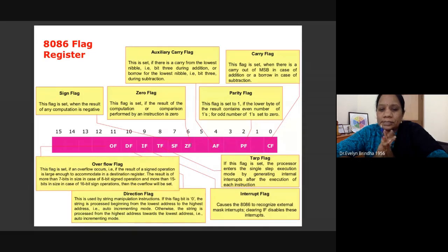That is possible. This is just one example. I'm telling you where these flags can be used to take some decisions. Okay? If the subtraction ends in zero, suppose your zero flag is made equal to 1, then we can decide both are equal. A is equal to B.